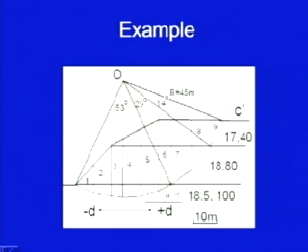And for any slice, for example, let us say slice number 7, this is the inclination of the failure surface with horizontal, which I have denoted here by angle theta. The soil is not homogeneous. Here gamma is 17 kilonewton per meter cube. It is 18 here, 18.5 here. C dash is also different. So, it is 40, 80 and 100 kPa.